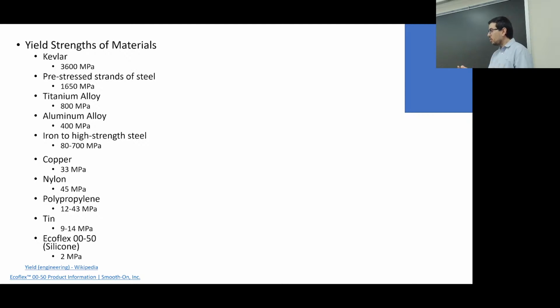Well, it turns out that we can plastically deform the material, okay, and cause its yield strength to go up. And how do you plastically deform a material? You could just, for example, hit it on the outside. This is like shot peening, essentially, a bunch of balls being fired at it, and it induces a lot of little divots, and that increases the strength on the outside.